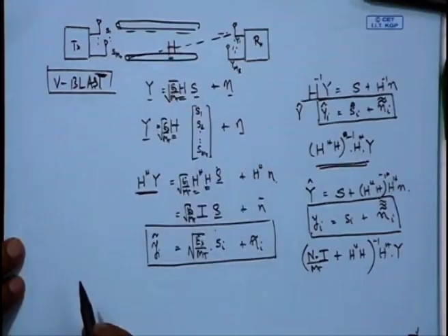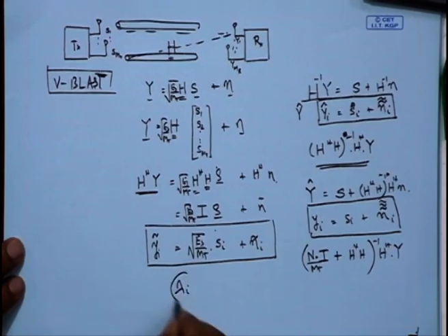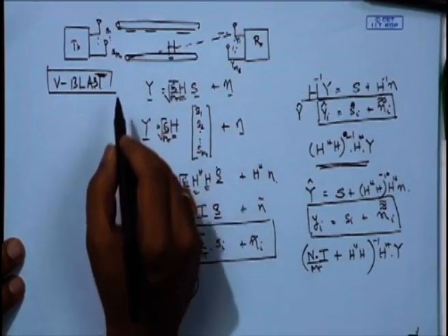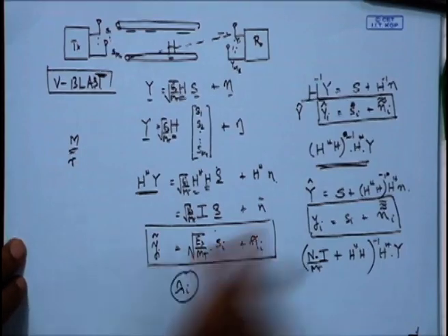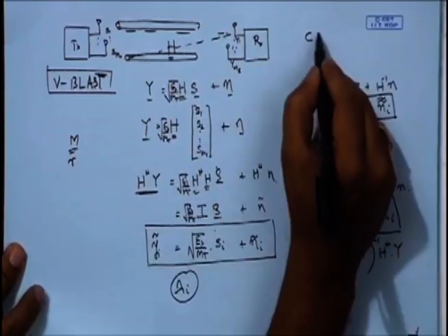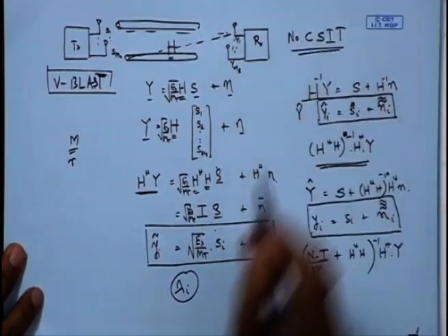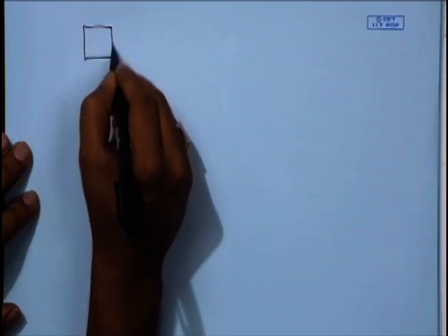And we would remember that this SNR is dominated or is indicated by lambda I, where lambda I is the eigenvalue of the ith channel mode. So if it is a square matrix, you have m parallel links or you have r parallel links depending upon the rank of the matrix. So this is one mechanism where you can achieve parallel data transmission when there is no channel state information at the transmitter. We move on further after this to look at the second scheme, where channel state information could be made available at the transmitter.